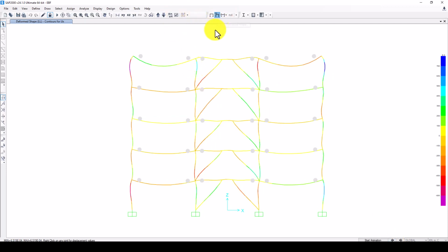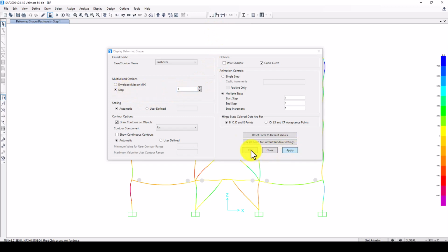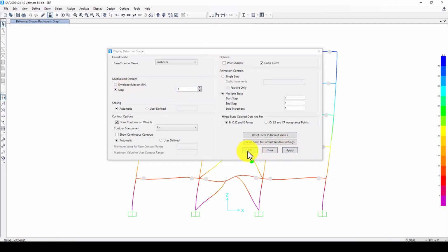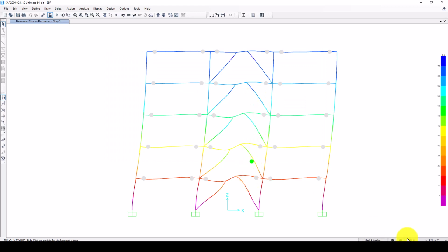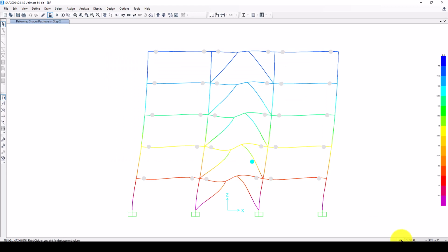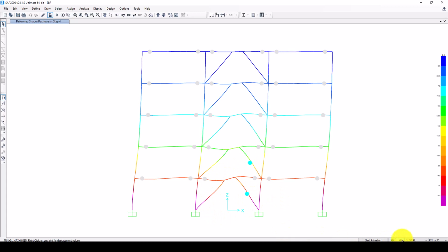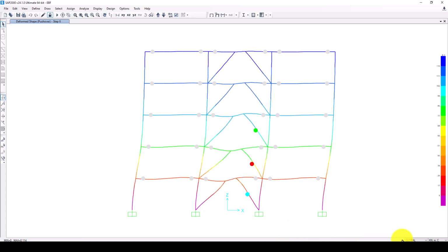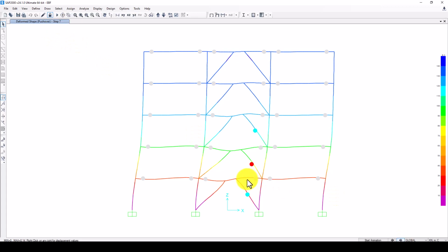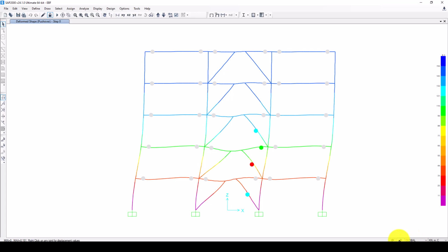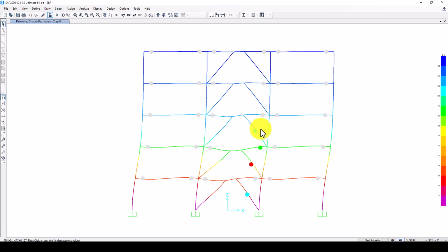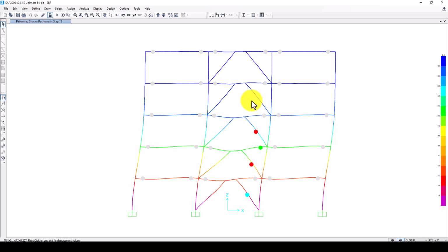Let me use the steps. Come to here, steps, and it's step 1. In step 1, we just have 1 hinge. Second hinge, this means the hinge location, and the second hinge appeared from life safety to collapse prevention, and we increased to step 7, and we can see the first one. This one is collapsed, and we can go further. So 10, 11, 12. So each step.